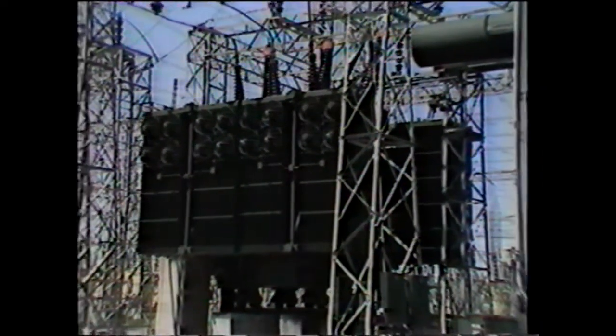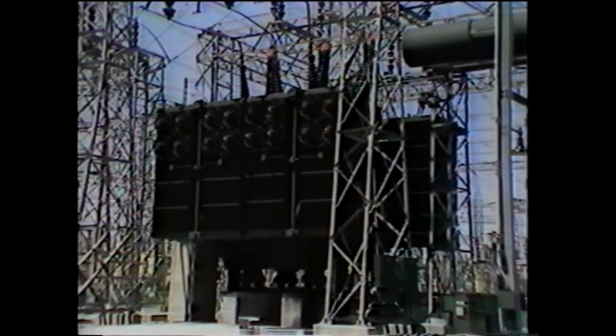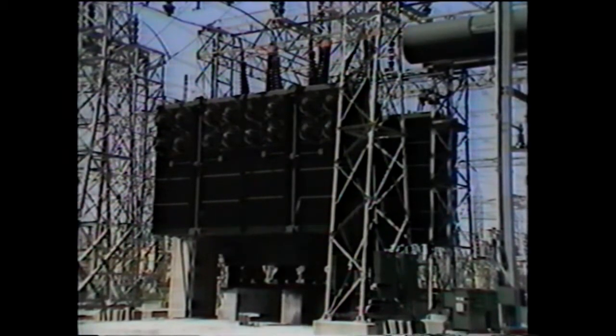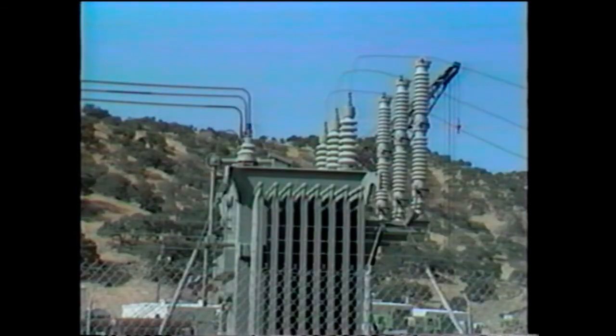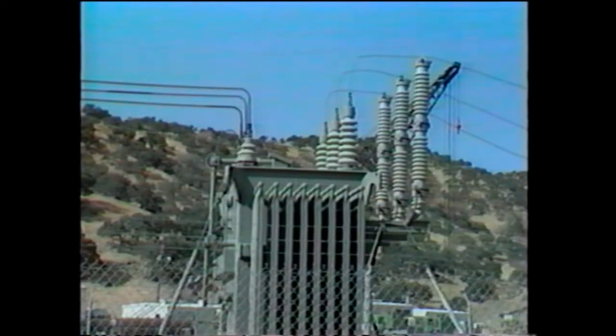Transformers are used all over the power system at all voltage levels and in sizes ranging from, say, 3 kVA up to 500 MVA. Generally, power transformers are three-phase. That is, the primary and secondary windings of each phase are wound on 3 legs of a common iron core, all immersed in the same tank of insulating oil. Single-phase transformers are also used, connected to form a 3-phase bank.